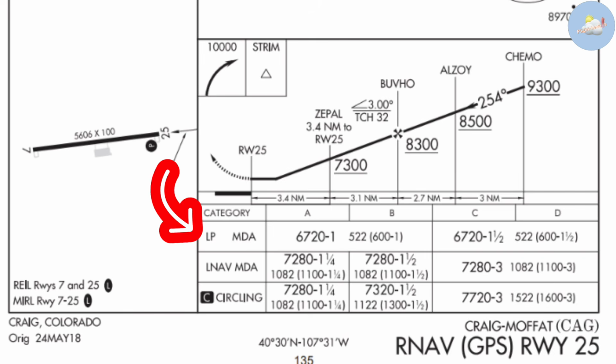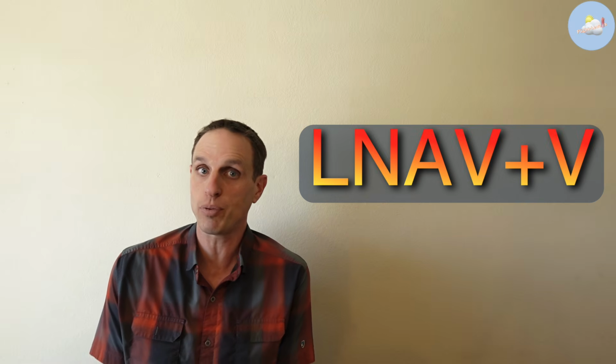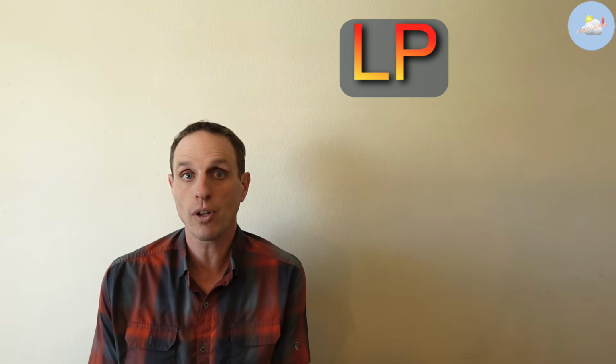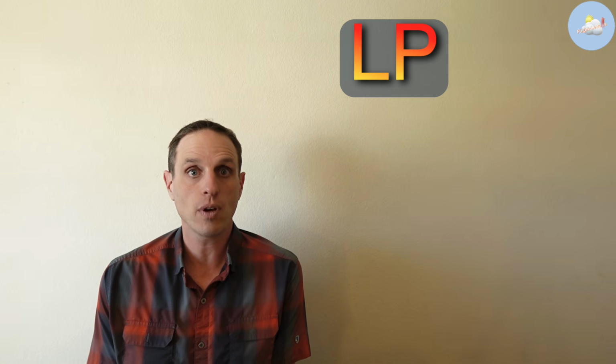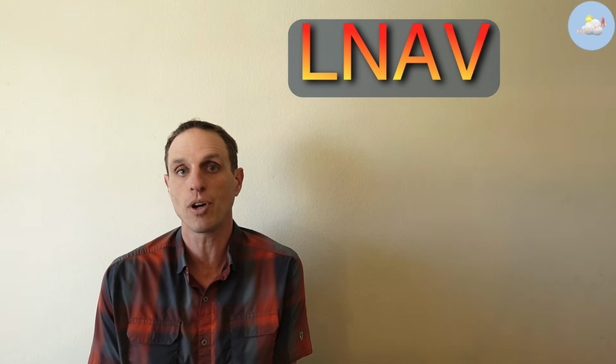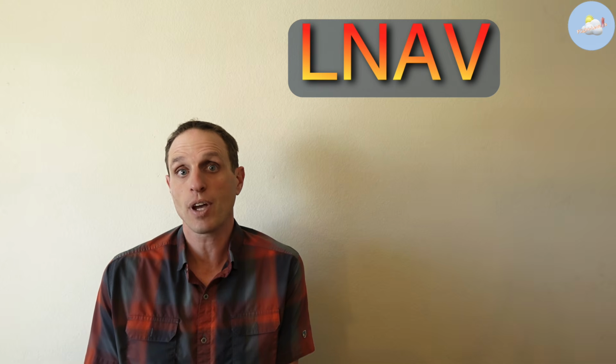Next, the approach you're using, like we talked about, needs to have either LP, which is localizer performance, or LNAV minimums. Now, I bring this up because in recent memory, everybody has been calling this LNAV+V, and it's important to know that +V can also be applied to LP approaches, which is localizer performance. The difference between the two is that localizer performance ramps down in how wide the CDI deflection is, just like an LPV approach, whereas LNAV approaches are a fixed 0.3 of a mile either side of centerline.